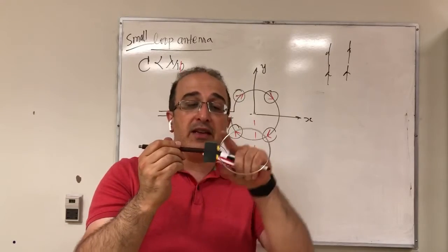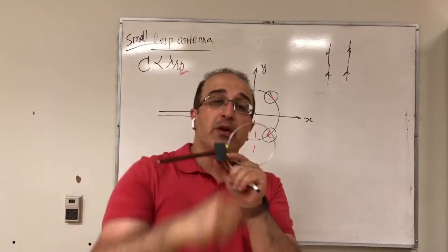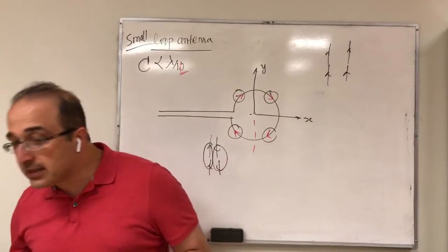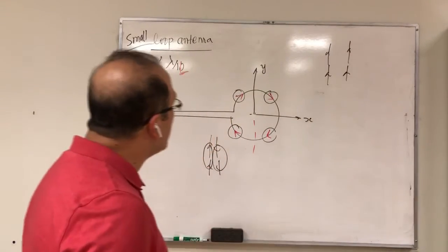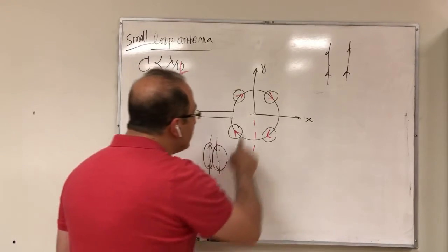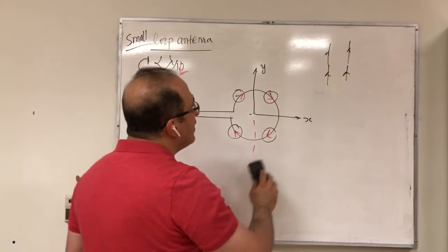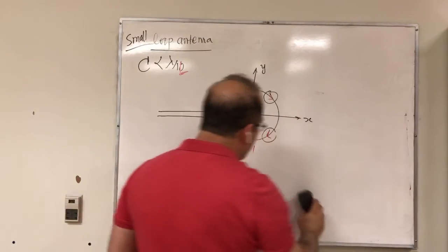Whereas if the circumference is about one wavelength, in fact, I have maximum radiation toward you. So this is what we can learn from this loop antenna. Now, this is the null here. Now let's do another example, and now let's go around the loop.